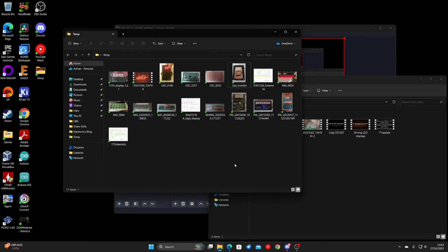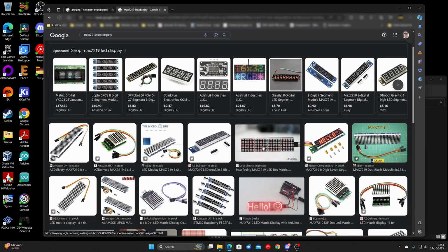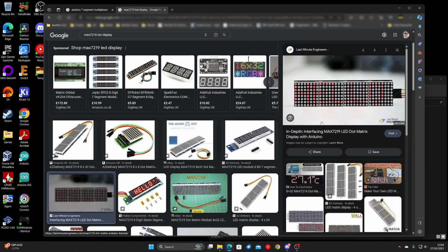And then finally, that's pretty much it for 7-segment displays. For dot matrix displays, the only method you can use with them is, again, I would just recommend buying a MAX7219 based display. It's the cheapest chips and you use a library. There's really no other option to that, unless you're trying to get a salvaged unit working like I did.